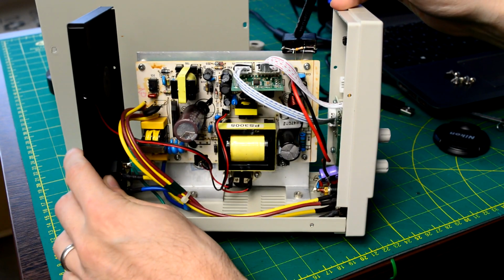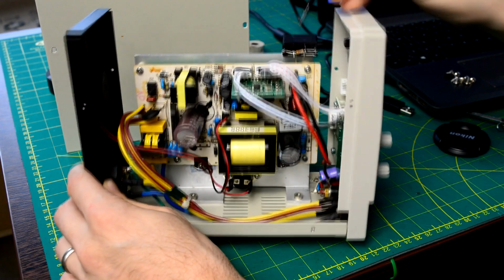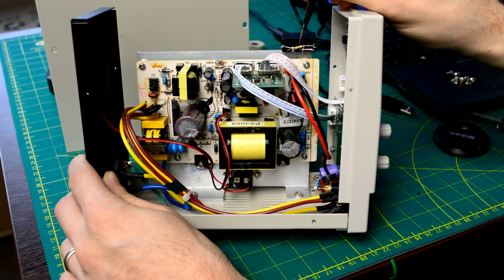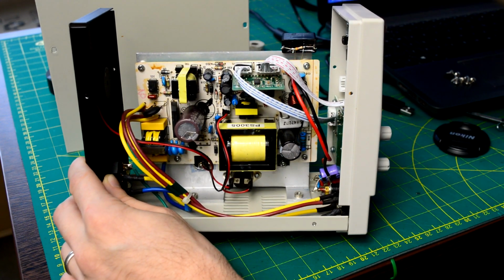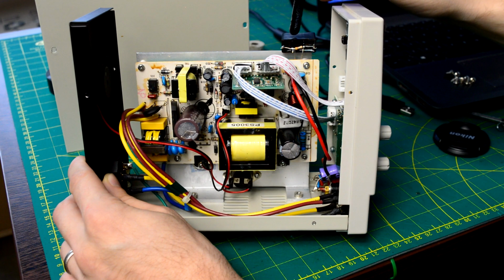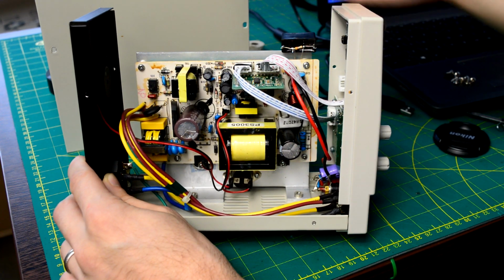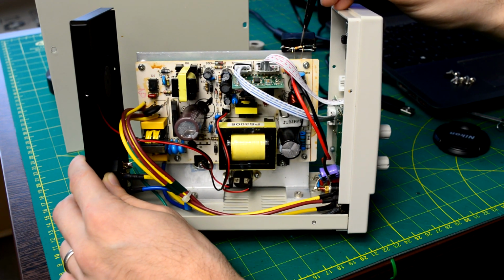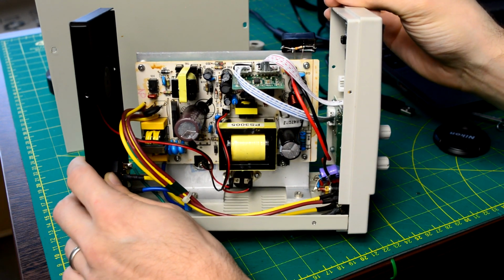So I added the capacitor from the ground to the protected earth. So this is the 470 nanofarad capacitor, but I also added an extra resistor. So this is a 4 megaohm resistor, and the whole point is that you don't want this capacitor to charge up with certain voltage that could discharge and create some damage. So it's common practice to also add such a resistor to unload the capacitor, but a high value resistor, so not 100 ohms or something.